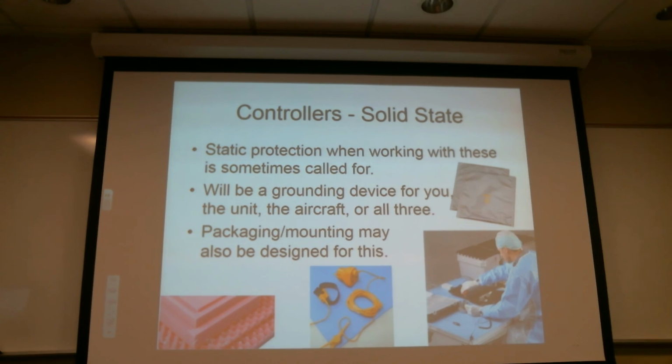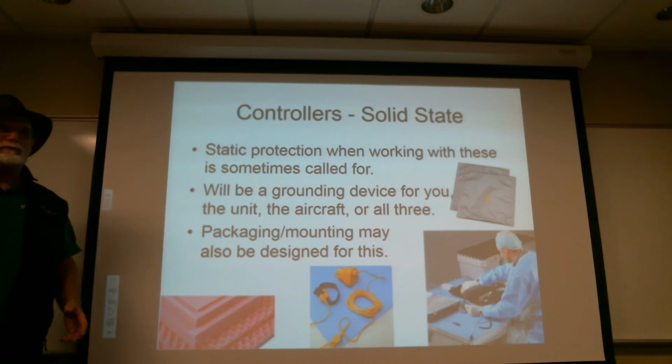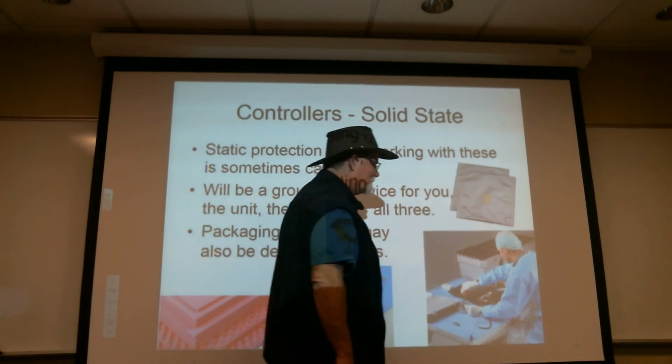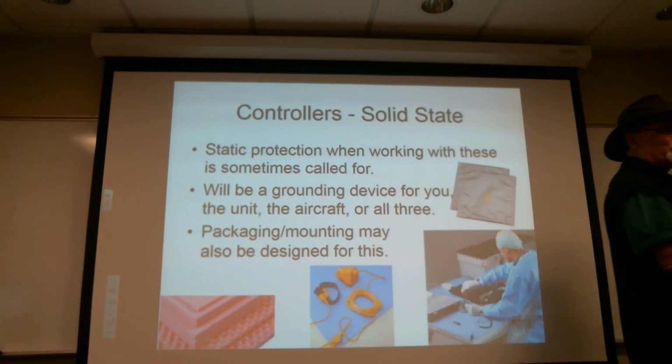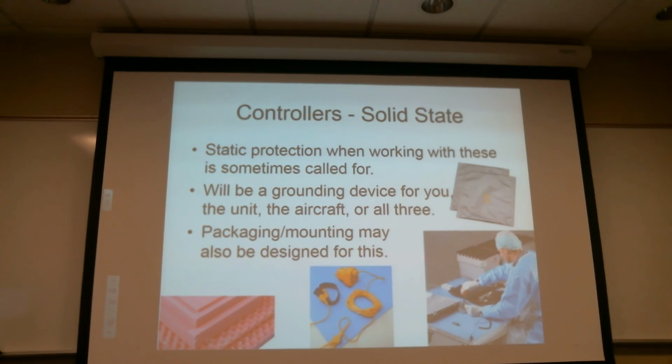Oh yeah, okay, so just a couple more. If it comes in one of those funny little plastic foil packages, plan on putting the strap on, okay? Now, I don't know about the cool little nurse's hat and the blue uniform. That's kind of cool. I guess if you want to look cool, you can put all that stuff on. Truly, that's not about static protection. It's about contamination, debris and stuff getting into the equipment.